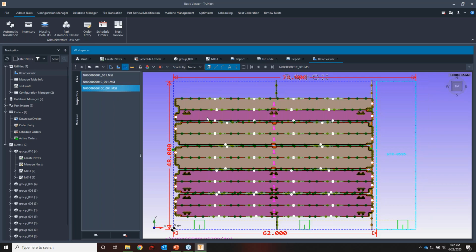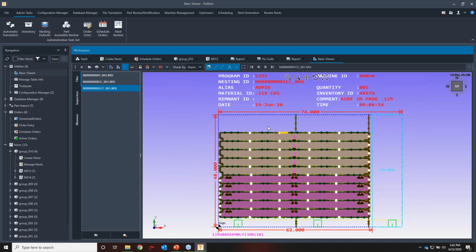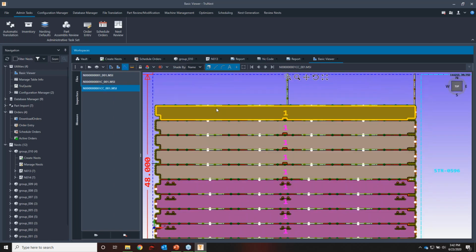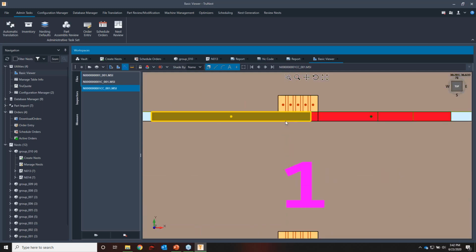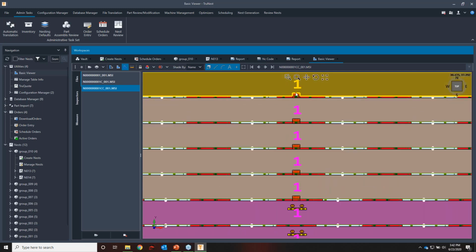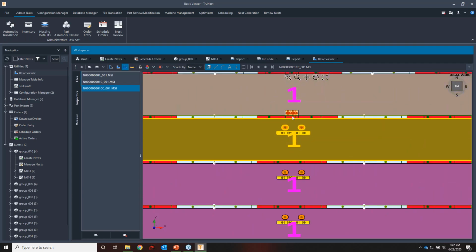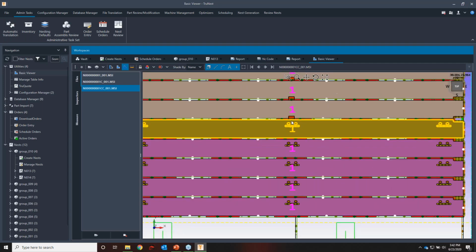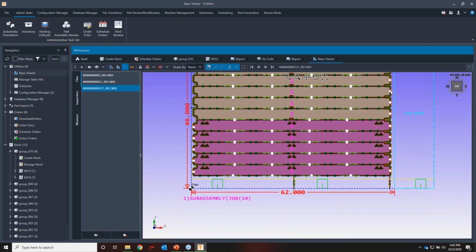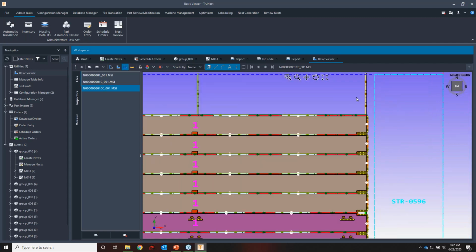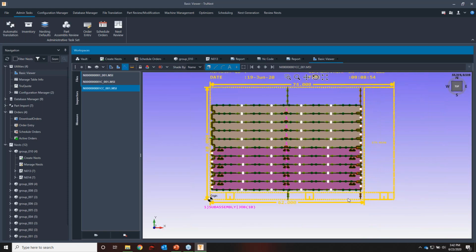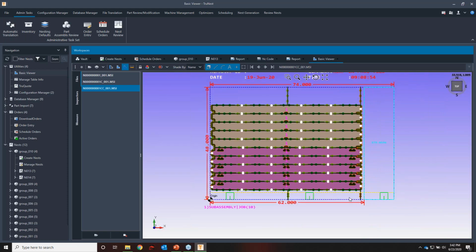And then a full common line situation, you can see now all the parts are full common line in between them. Again, we run into these situations where we need to make sure that we destruct the material between the parts in order to make sure that the sheet is processed accordingly. But in this case, we're going to save the most amount of punches since every line between these parts is shared. You can see the difference in material utilization as well.